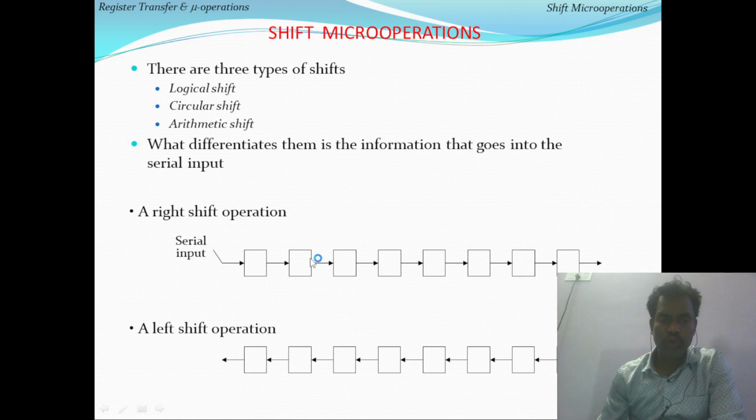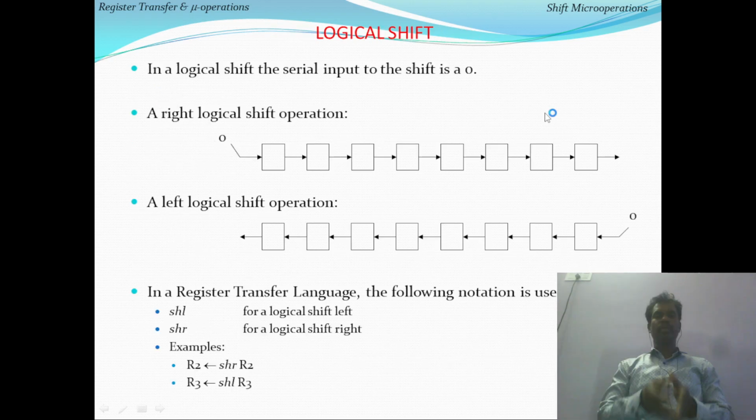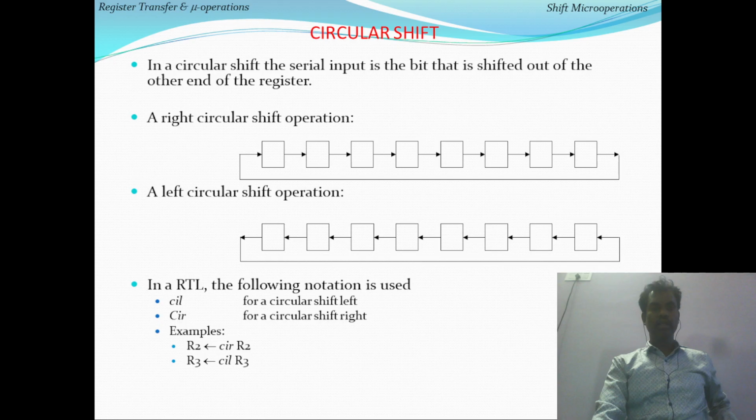Similarly, instead of logical shift, there is also the arithmetic shift. The MSB has to be kept as it is. We copy the MSB as it is and perform the right shift. The MSB generally indicates the sign of the data, and we don't want to change the sign by performing a shift operation. If it is positive, we copy the 0 as it is. If it is negative, the MSB is 1, so we keep MSB 1 and do the right shift. In left shift this doesn't happen.